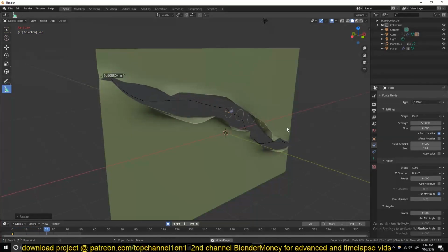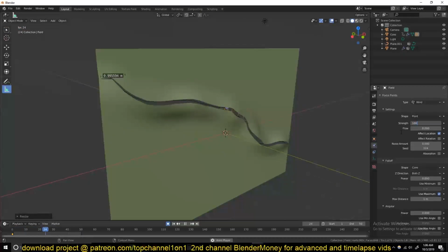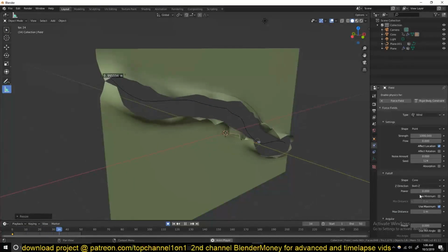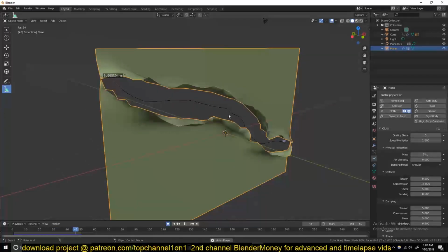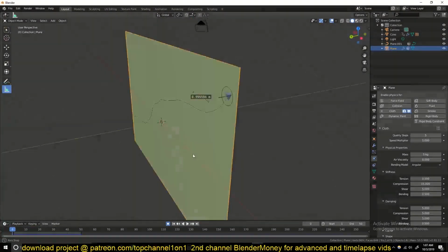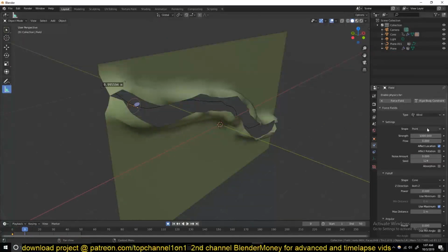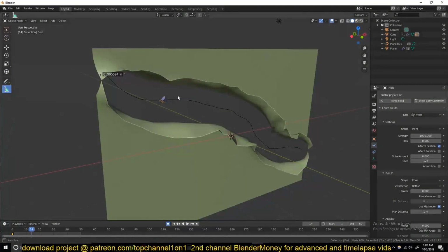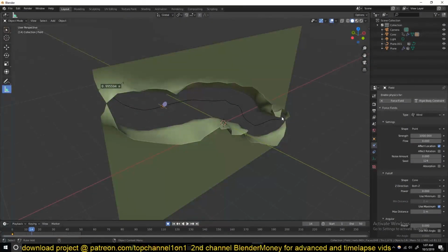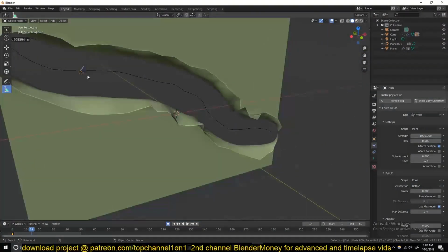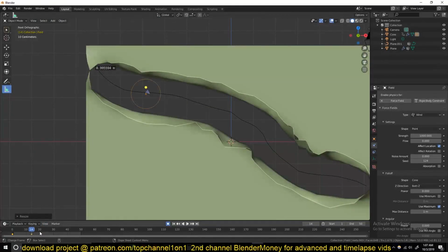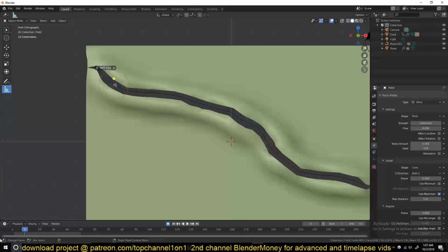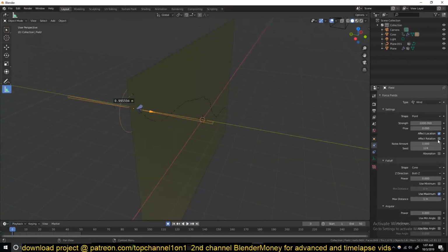You also just want to affect the location of the vertices. I think 100. Apply scale. I want this air to start blowing, not to blow the entire cloth at once. So make sure of this. Let's first turn off the location, and we'll see what is affecting. Affect location.